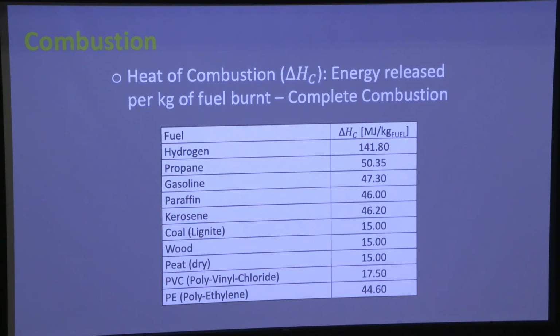So it's pretty straightforward. If the material is charring, effectively you get a heat of combustion of about 15, and if the material doesn't char, you get a heat of combustion of about 45 plus. Okay? So there's no great science in there other than just simply getting it out of a test. Okay?